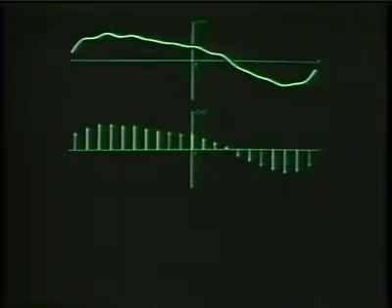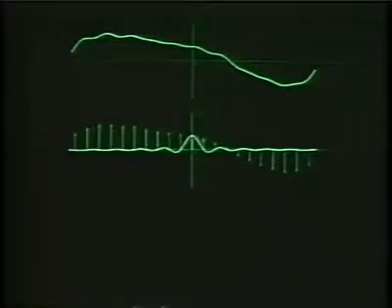The reconstruction process, interpreted as interpolation, consists of replacing each sample with a sin x over x function. And so let's first consider the sample at t equals 0. And here is the interpolating sin x over x function associated with that sample. Now, the more general process, then, is to place a sin x over x function at the time location of each sample and superimpose those.